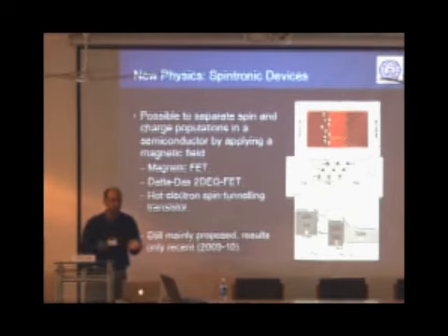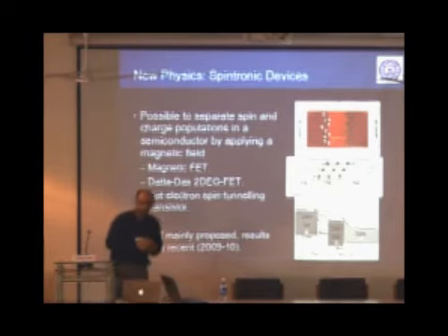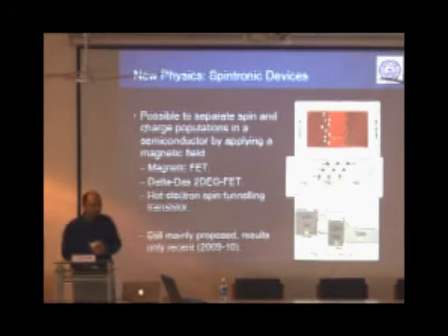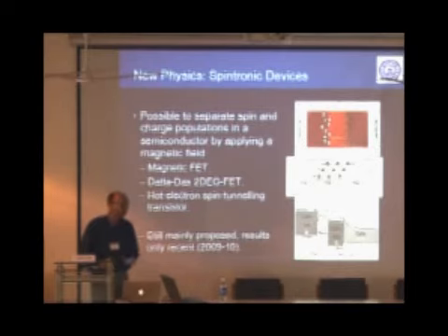The spin up and the spin down channels, there is a major amount of scattering between the two. The probability of scattering electrons from spin up to spin down or vice versa is very high. So in the case of gallium arsenide, the spin relaxation lengths are very long. Very long in the sense that all you want is several hundred microns. You don't want more.